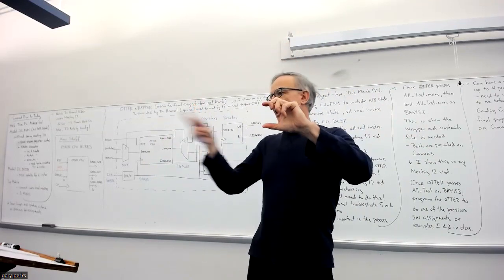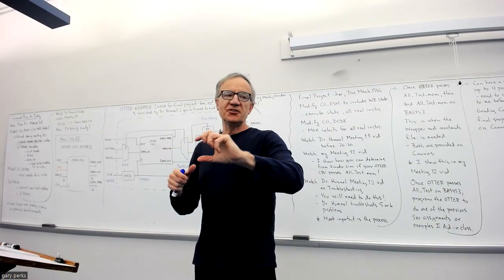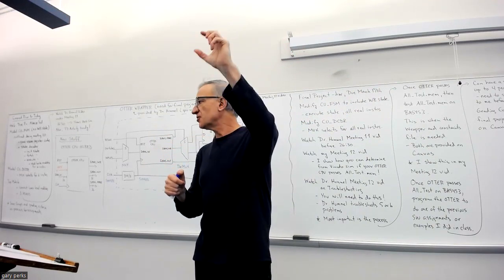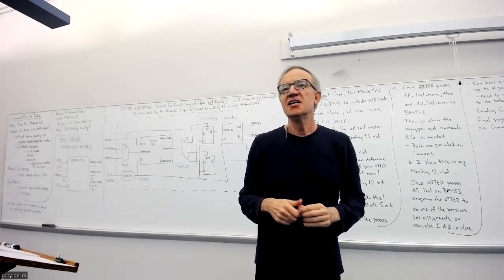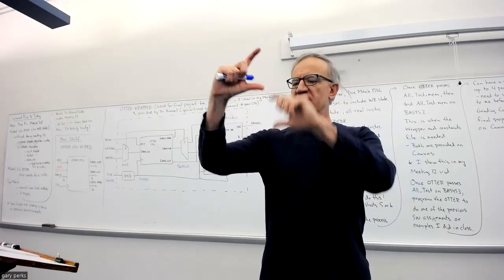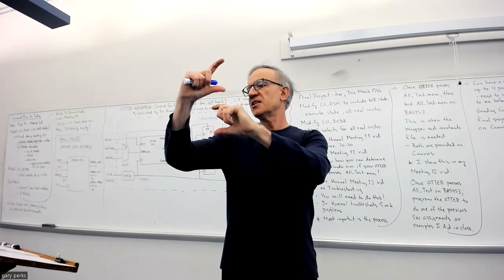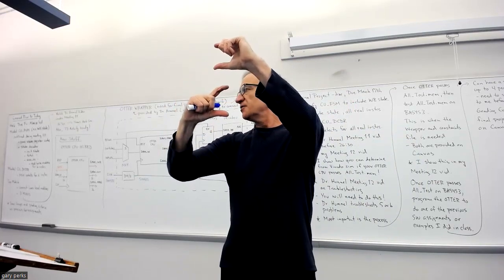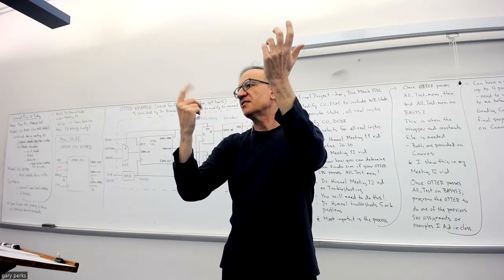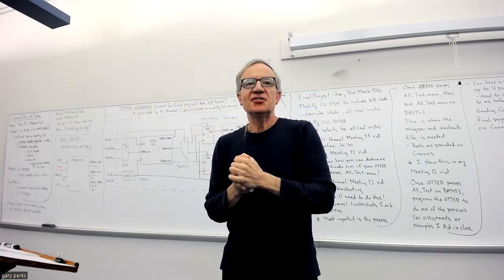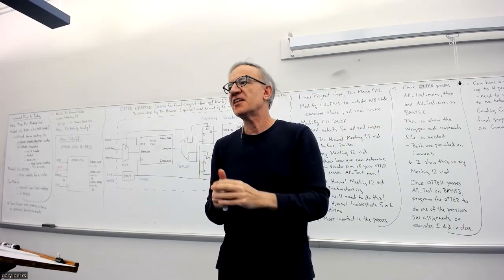But what it ended up being was the assign statements for the async reads. My understanding is it doesn't matter where you put those assign statements in your Verilog, because they continually happen. But for whatever reason, when it wasn't working, the assign statements were below the always FF block where the synchronous write was. All I did was put those assign statements for the async reads before the always FF block, and that fixed it. But it seems to me that it shouldn't have worked either way. So I'm not sure why it fixed it, but it did. Sometimes weird stuff like that happens.